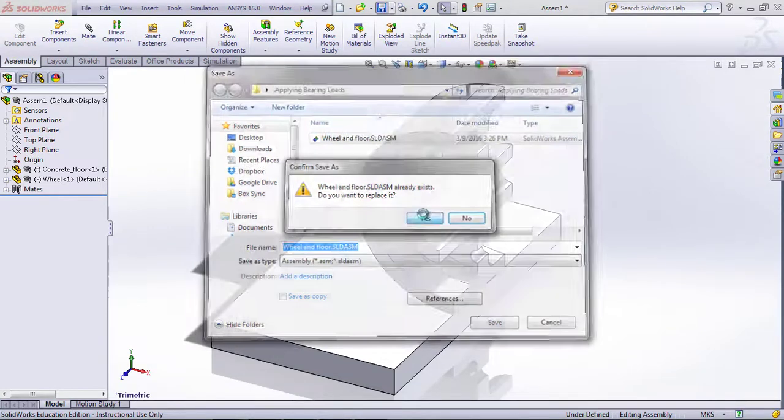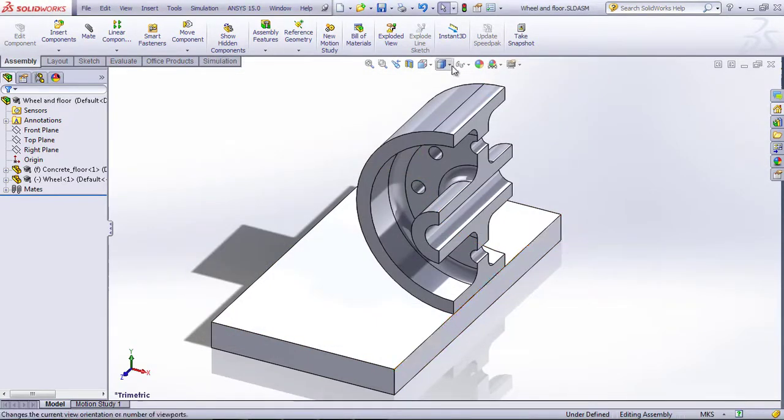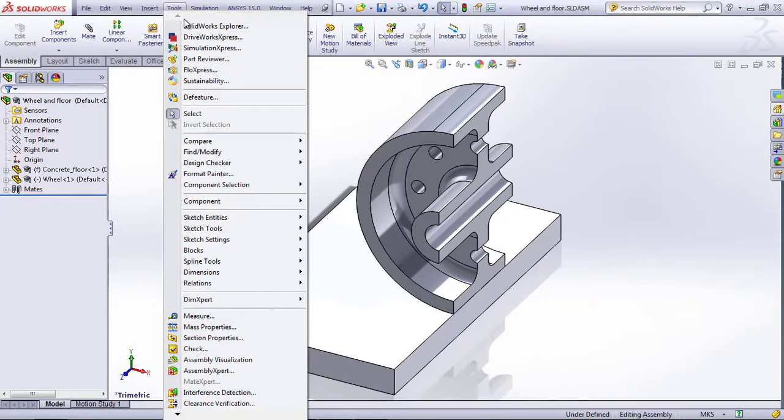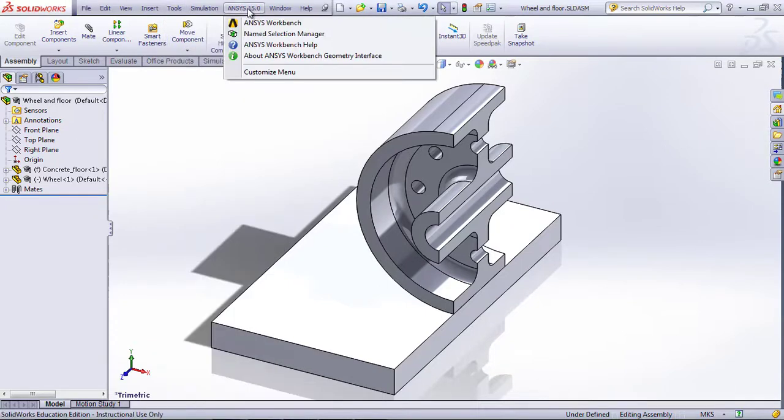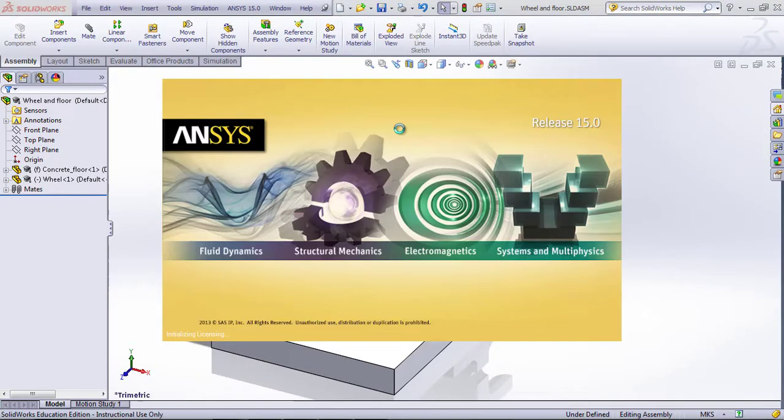All right, so now I can take it into ANSYS. And actually, I was looking at SolidWorks 2015. I'm using 2013. So ANSYS shows up here in my version, obviously. I believe in 2015 it shows up under Tools. And under Tools, I get the menu to show up here, a couple menus down, ANSYS. This is basically the same thing that will show up under Tools. So if you have that, that may be where it's showing up. So I'll go ahead and take this into Workbench. Again, if you need to, you can save it as a STEP file and bring it up into Workbench as a STEP file.